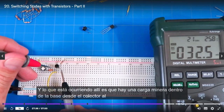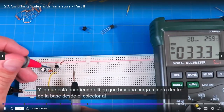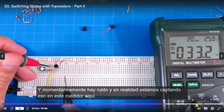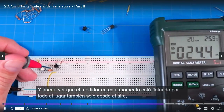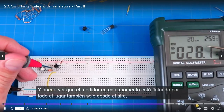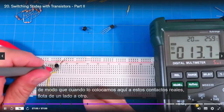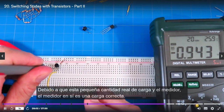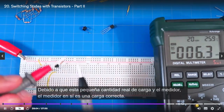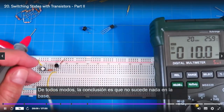It's just floating. And what's occurring right there is there's minute charge inside of the base from the collector to the emitter, and momentarily there's noise, and we're actually picking that up on this meter here. And you can see the meter right now is floating all over the place also, just from the air. But when we put it here to these actual contacts, it floats back and forth, because there's actual little minute amounts of charge, and the meter itself is a load. So anyway, bottom line is there's nothing happening on the base.